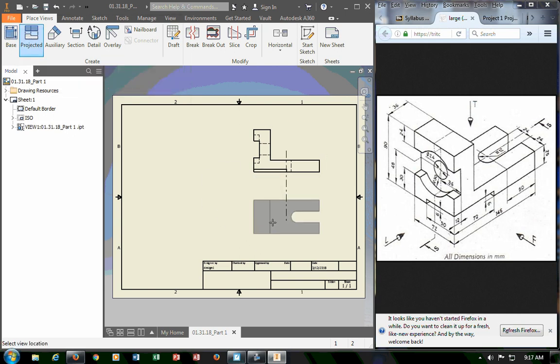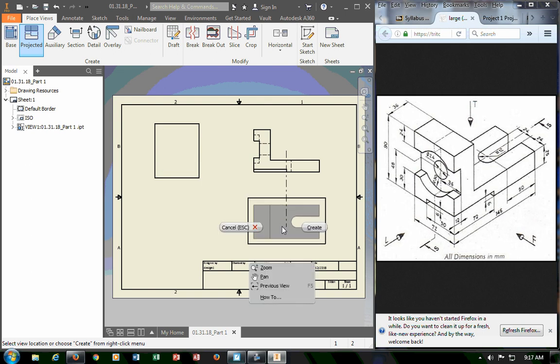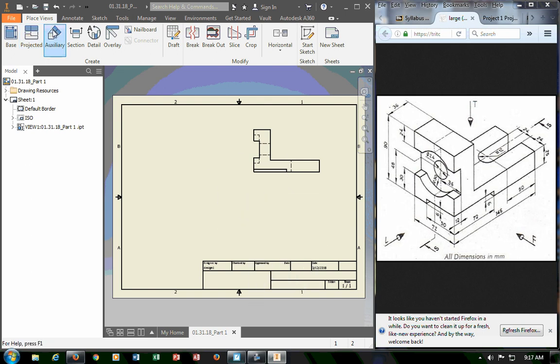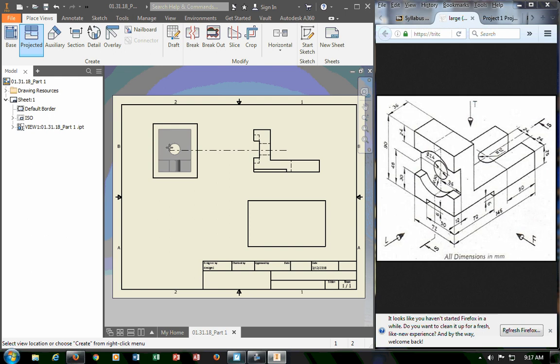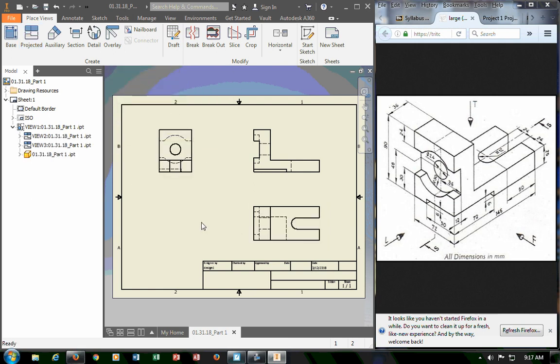When I project, let's see how this is going to project. Let me do that one more time. Sorry. Project geometry. This is the primary view. I drop it down because that's what's going to be my top view. And I go across to the left because that's going to be my right side view in the world of metric, where my right view is created. So let's see if it did it. And it did. Did a good job.